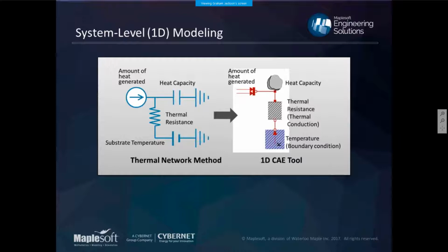It helps you create a fairly intuitive model that represents your thermal problem still as a thermal problem, so not having to switch it to an electrical problem. And the library we're using supports everything you need in terms of convection and radiation. So the 1D simulation tool is going to be great for this, but it has drawbacks as well, in that for many people who aren't already acquainted with system level modeling, it can be a difficult methodology to take on for complicated projects.